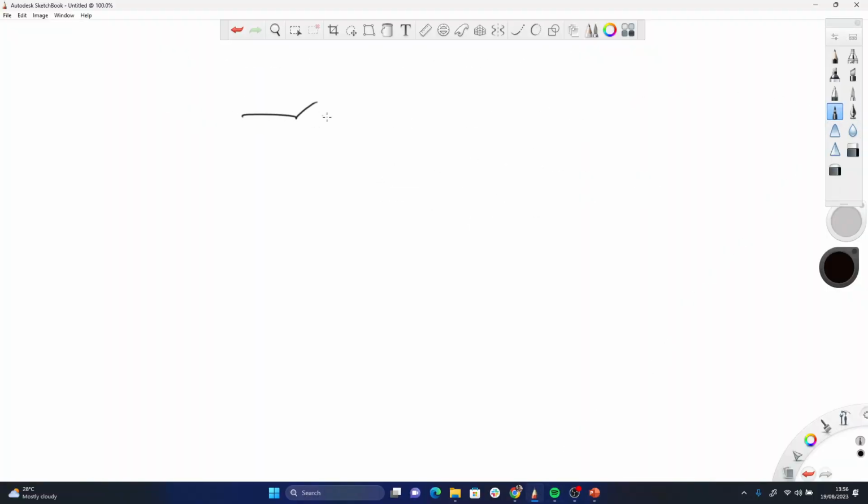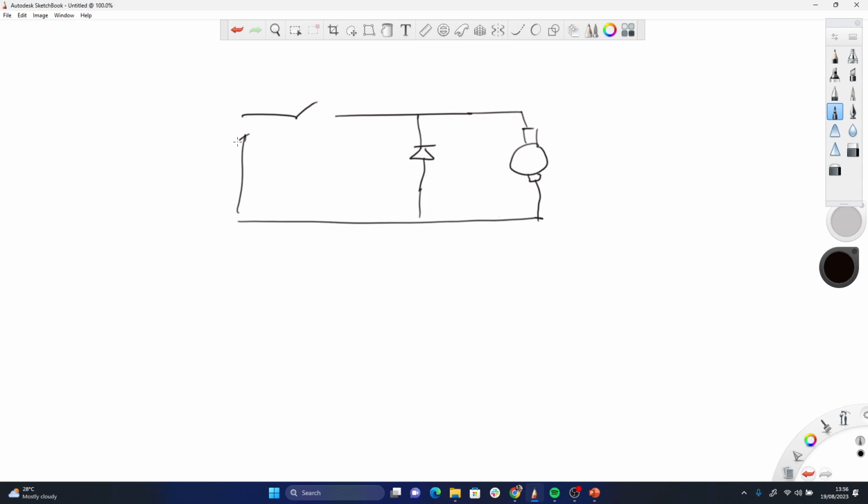This is how it works. I have a switch. I have a diode connected like this. I have the armature here. So I have the supply voltage Vs here. This Vs gives a certain V naught, a certain voltage, to the motor. This is a switch. The motor draws a certain current Ia. This is the source current Is. Now I can control the frequency of the switching by pulse.